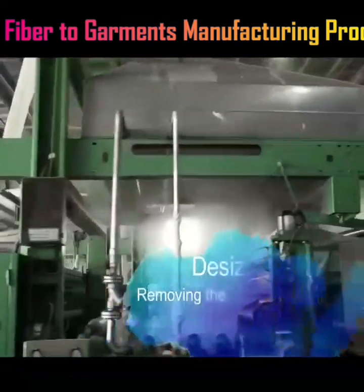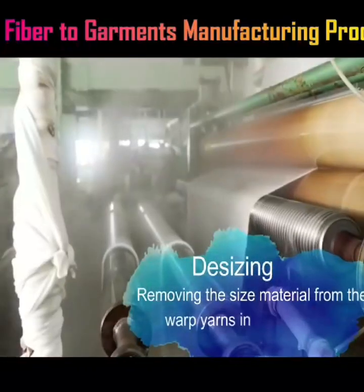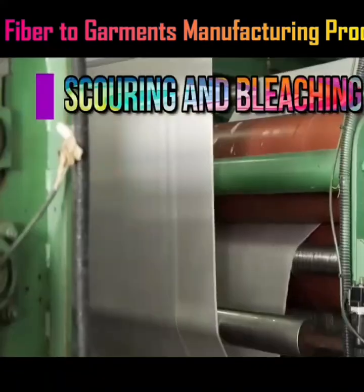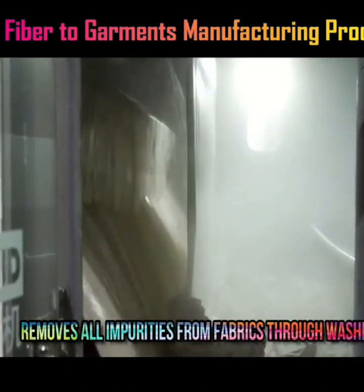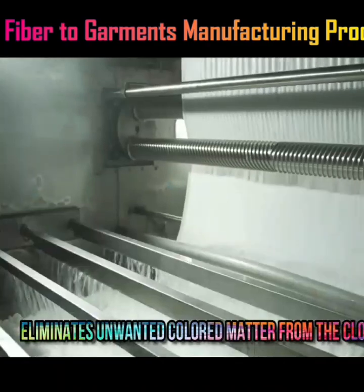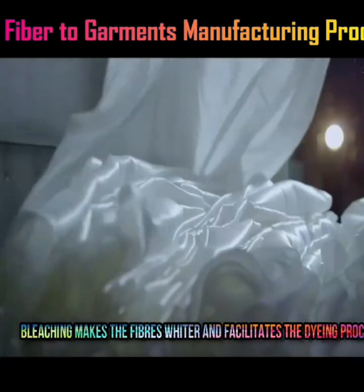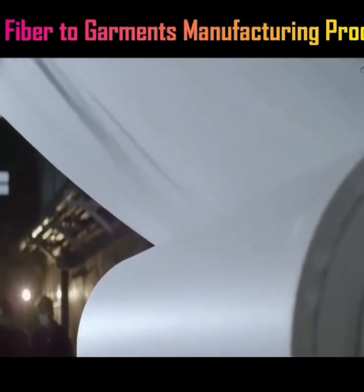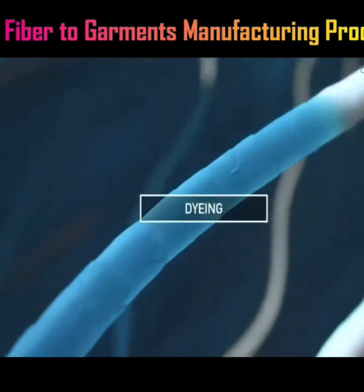Desizing. Desizing is the process of removing the size material from the warp yarns in woven fabrics. Then the fabrics go through the scouring and bleaching process, which removes all impurities from fabrics through washing and eliminates unwanted colored matter from the cloth. Bleaching makes the fibers whiter and facilitates the dyeing process. It also makes the fibers more absorbent. And finally, cleaned and white fabrics are transferred to the dyeing section.